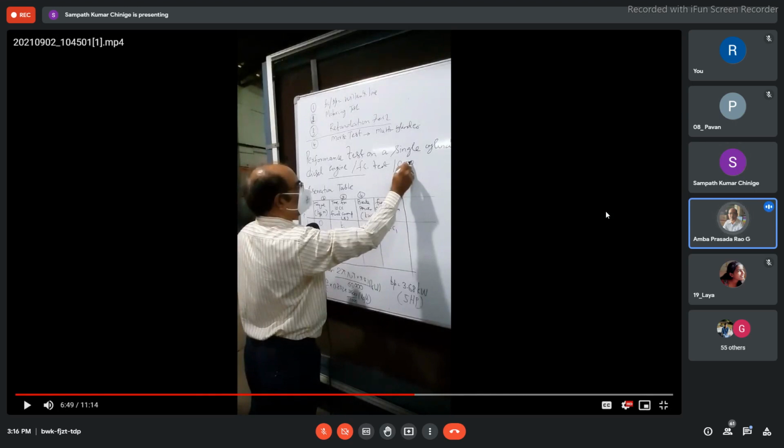So power developed inside the engine cylinder, and power developed outside at the crankshaft, which is available to the user end. The difference between these two is friction power. So this is the direct method. All these four methods listed here we can compare with the help of this direct method. That means it requires sophisticated instrumentation like a pressure transducer and crank angle marker, so that one can arrive at the indicator diagram.